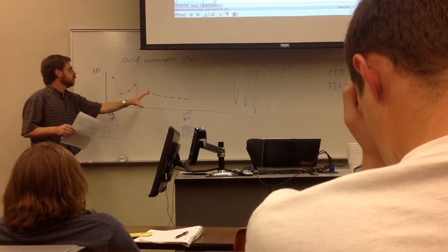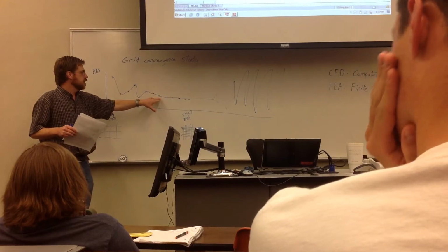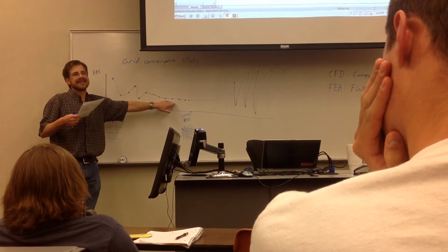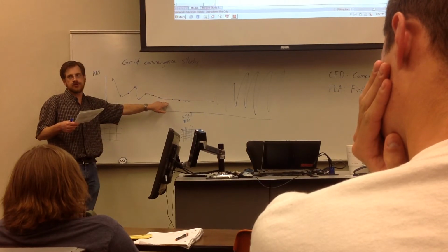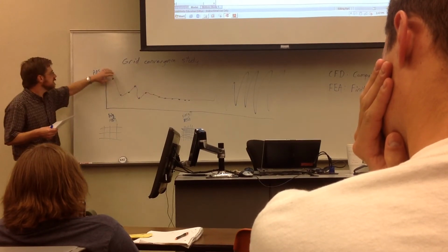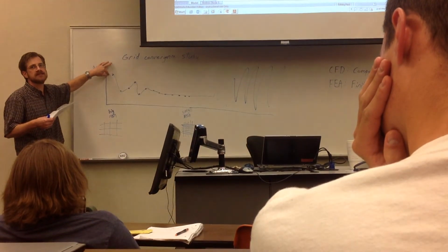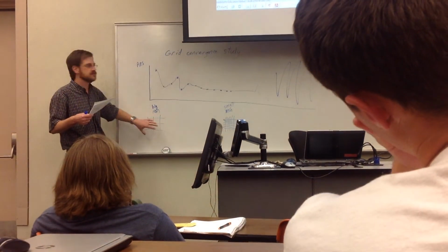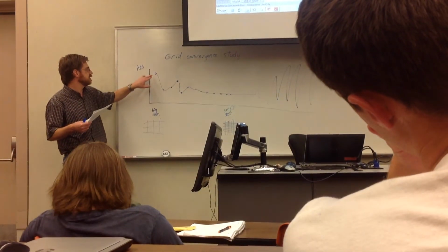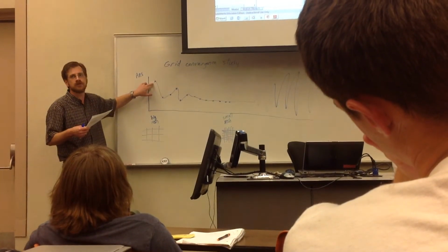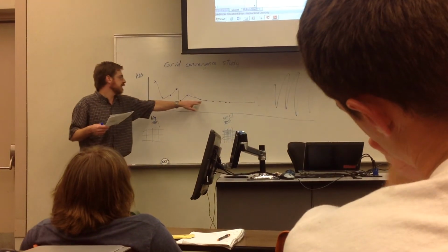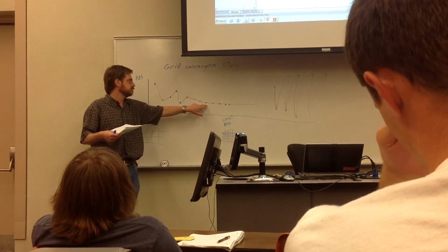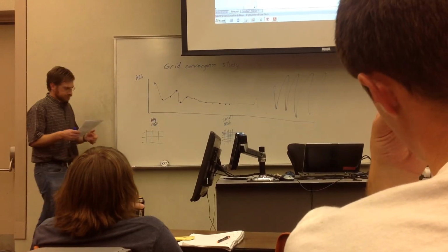And what you're looking for is the point at which the answer you're getting is independent of the mesh size that you're choosing. Okay? This answer up here is a bad answer because the answer is dependent on the mesh size. The mesh does not accurately represent the problem and does not give you a correct result. By the time we get out here, this is starting to look more like a correct, viable result.